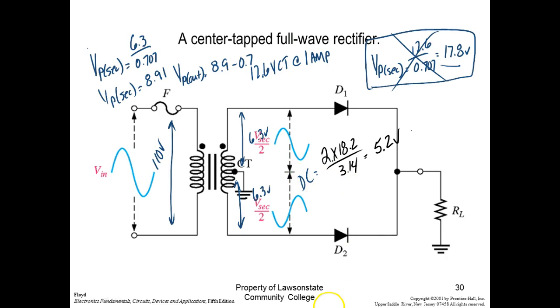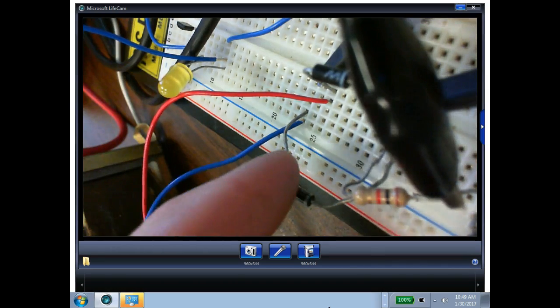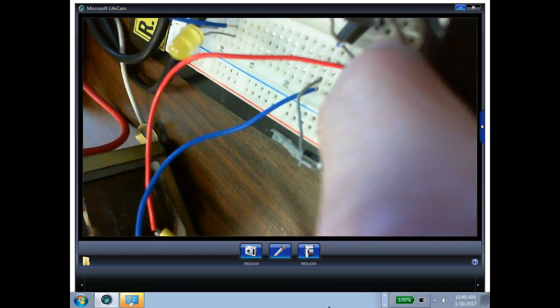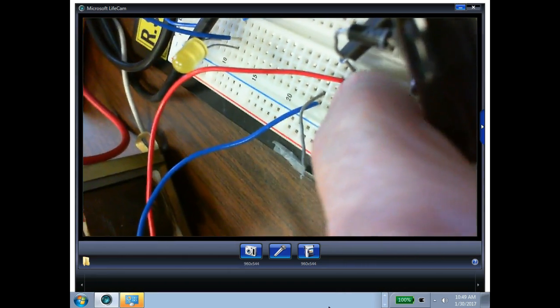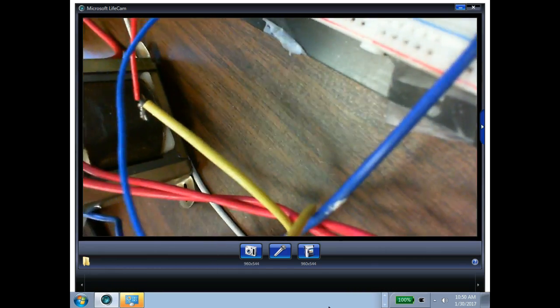So what I have here, of course, that's why my anodes are in different vertical lines. Can y'all see that? Here's this one right here, and here's this vertical line, and there's that one right there. If they're in different vertical lines, the vertical lines are not connected together. Anything I want connected together, I hook in the same vertical line. If I don't want something hooked together, I hook them in a different vertical line, right? Does that make sense?